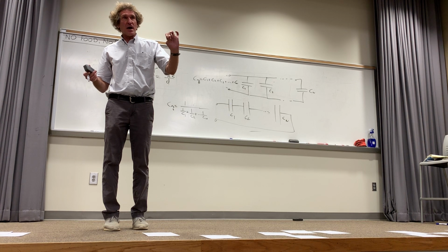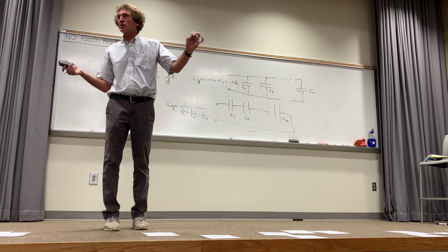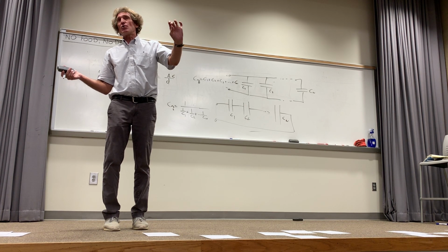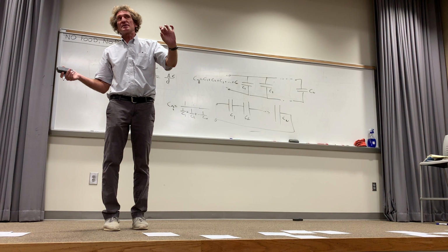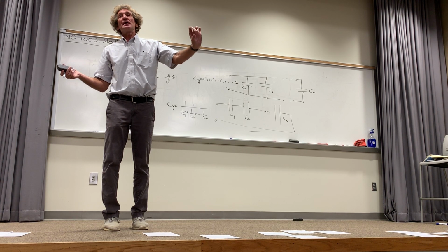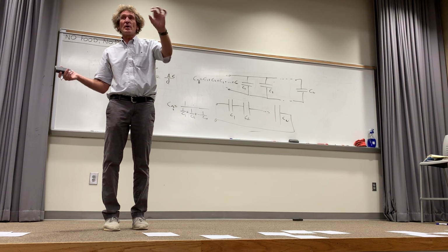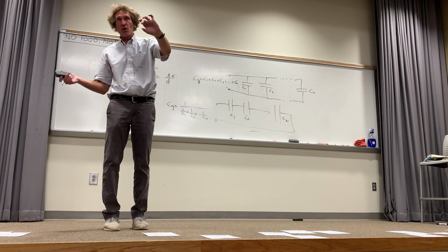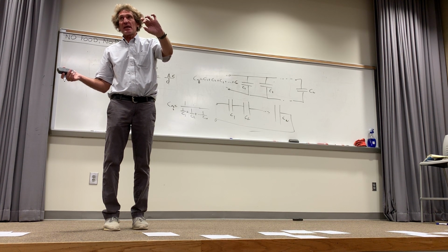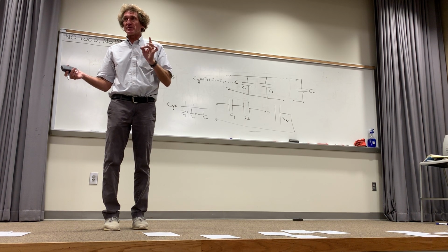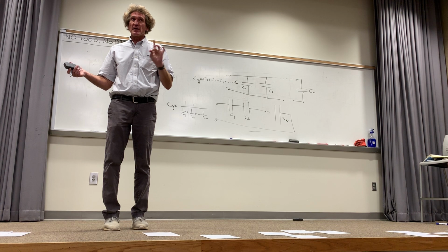Mechanical engineers use scopes and other measuring equipment. The scope has a certain capacitance at the input. That capacitance has to be accounted for in any device you connect for a probe. So the probe capacitance and the capacitance of the actual scope have to be added together in parallel. You need to know that or else you're going to make some measurement mistakes for anything that's got high frequency variation. Just keep that in mind.